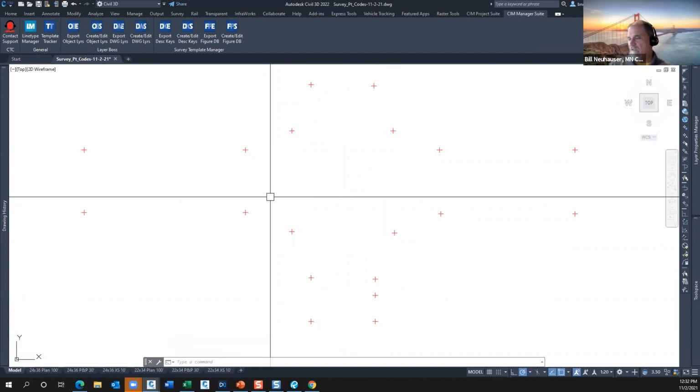I don't see the elevation description, but that's fine. I can go back and turn that on manually if I wanted to. The idea is that all I'm seeing is all the dots. And usually the next step for the operator is to come through and connect the dots, maybe doing break lines for surface or whatever, but bingo, they're isolated. I'm off and running. We're good to go.